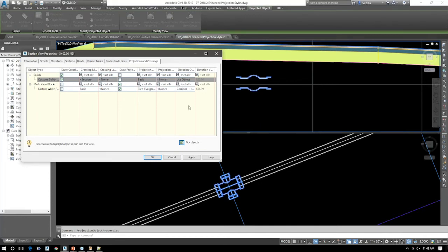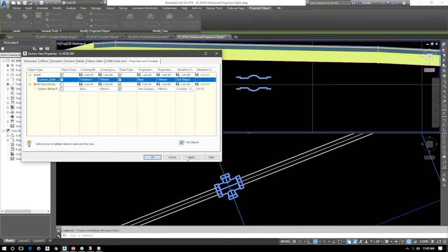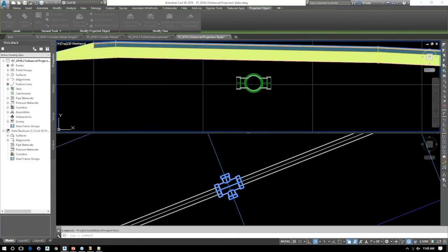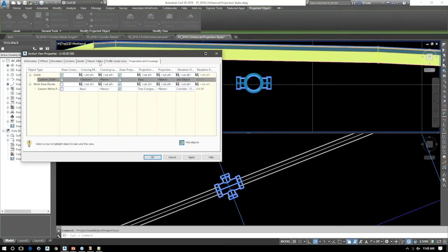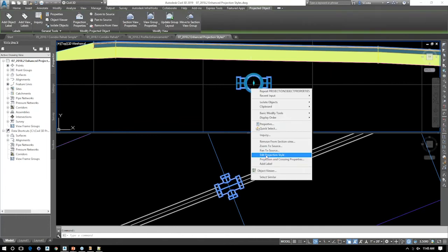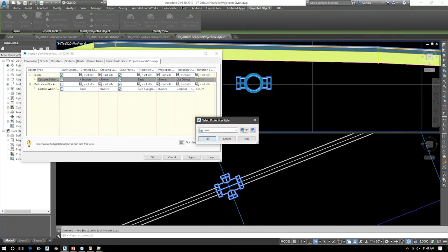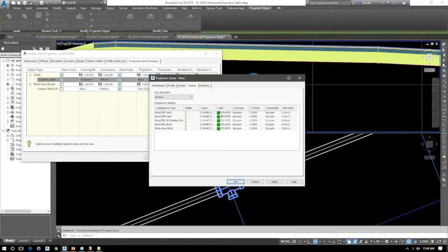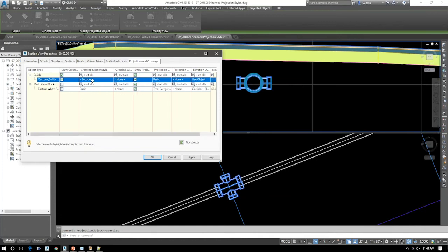So for example, if I put this in crossing, in projection, and I enable that to be drawn, this display is controlled by the style. So if I right click and go to edit projection style, how this appears is driven by, sorry, if I right click and go to, I could have sworn I chose the style, let's go to basic. And if I edit that, you're going to see that this display is driven by this layer and ultimately this property. The nice thing about this crossing marker style that has this special bracket section bracket is